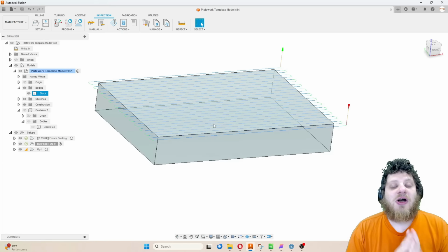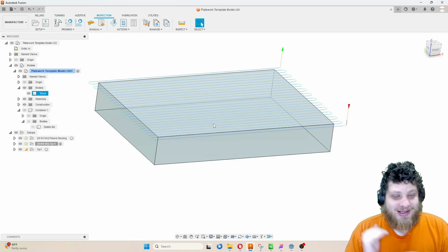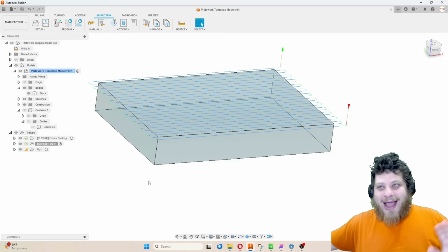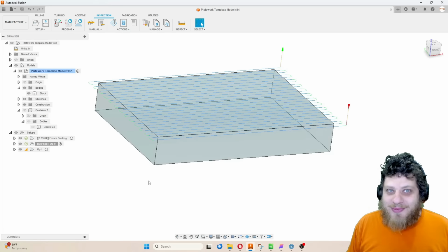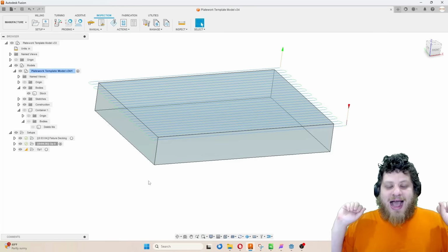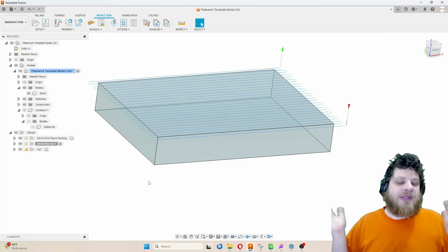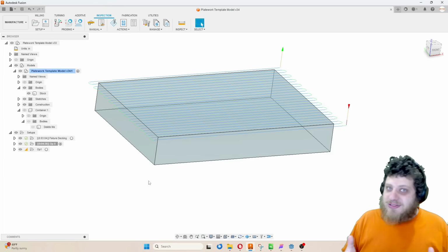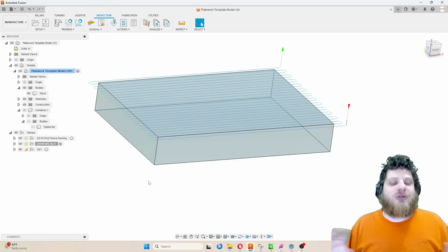So that was a lot of work to get set up. This took me a couple hours to record the CAD portion of this video. But now, whenever I run a super glue fixture part, I just drop the model into this, I regenerate my tool paths, I fix what's dumb, I add what's missing, and I hit post. Again, it won't cover everything I do, but it'll cover most of the tool paths for most of the parts I make, and that saves me a huge amount of time.